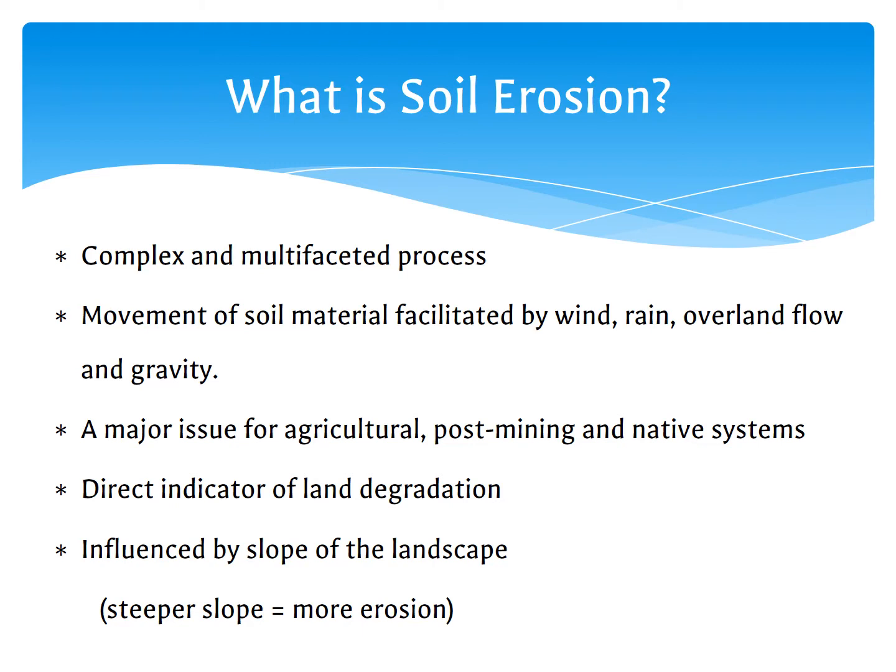Factors that contribute to certain soils being susceptible include particle size. The finer the particle, the easier it is to transport and hence move downslope. On the other hand, soils can be cohesive and sticky or non-cohesive, such as sand grains. External energy in the form of raindrops, turbulent eddies from wind and water, or gravitational energy can move a particle of soil. Soil erosion is also heavily influenced by slope of a landscape.